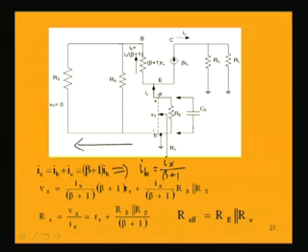So, what is this voltage Vx now? Vx is equal to the drop across beta plus 1 Re plus the drop across these 2 points. Now, the drop across beta plus 1 into Re is equal to the current Ib into beta plus 1 Re. Again Ib is equal to Ix by beta plus 1, into beta plus 1 Re. So, this cancels, plus the voltage across these 2 points is current Ib, which is flowing in this direction, into the equivalent resistance between these 2 parallel resistances Rs and Rb.